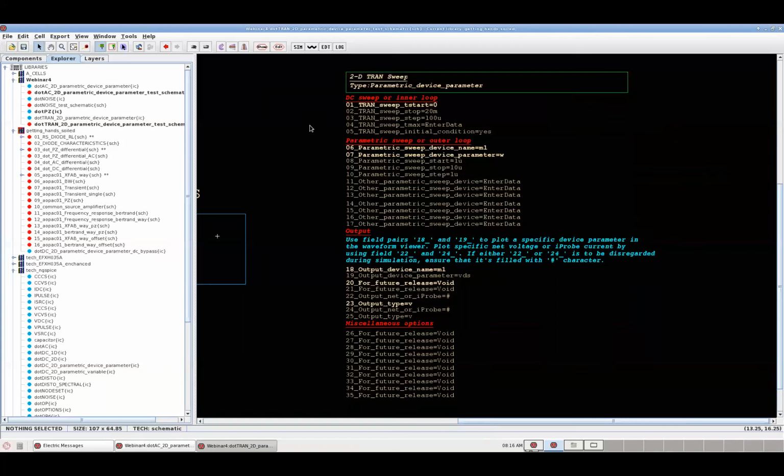And the initial condition is also a feature wherein if a designer chooses to have an undefined initial condition, that is to ask transient analysis to bypass the initial DC operating points and start with the existing node voltages and currents. You can choose whether or not to have the initial bias conditions.